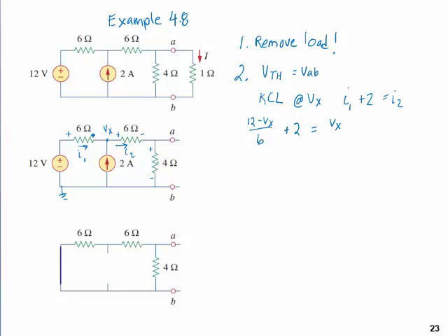So voltage up from here at that node I call Vx, and that current is Vx divided by 6 plus 4 ohms. So that's this current in this branch right here. And these are just measurement places. Nothing is going on here. These are just references to the node. So I have one equation here, one unknown Vx. I can do the algebra, and when I do the algebra I'll get that Vx equals 15 volts.